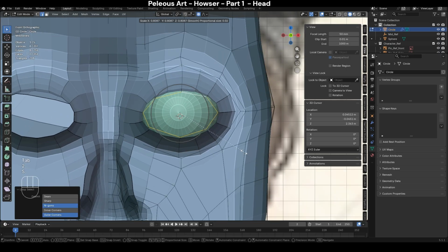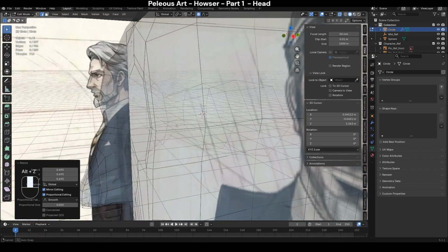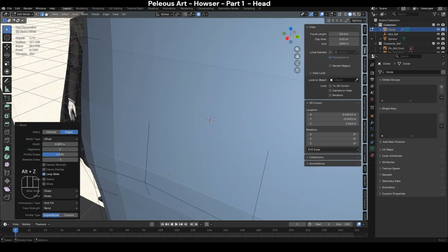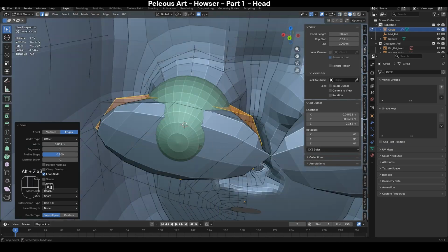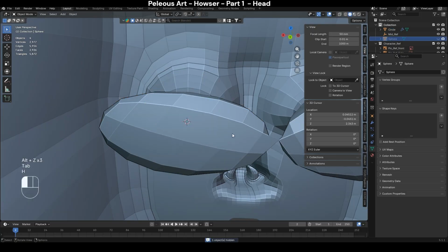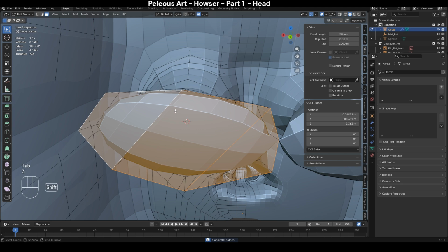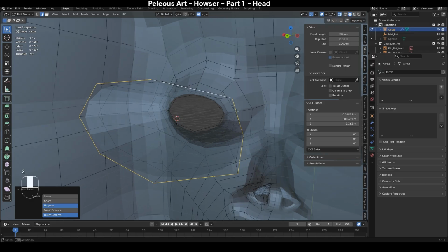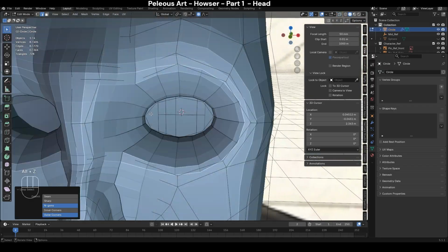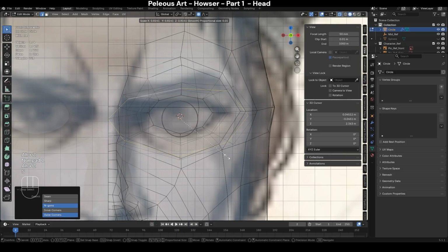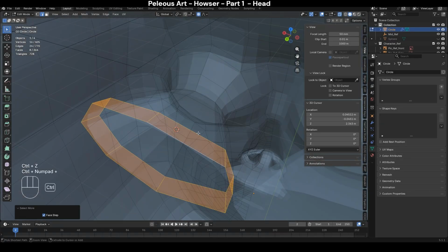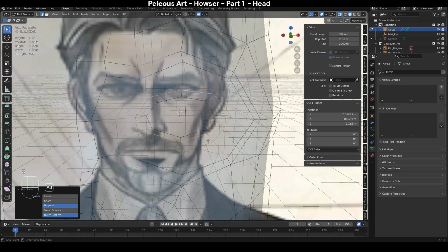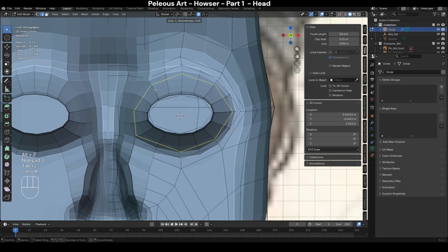Grab the edge around the eye, the inner one, not the outer one. You see what I did there? And then this one we're gonna bevel. So this one is the middle one inside the eye socket. You see the one that is marked. This one we're gonna delete because the grid fill is not what we've been looking for. So we'll select the whole edge, and we'll deselect. We'll scale it down just a bit. Let's Control plus to select, and then we're going to delete it. Then we'll do it much better later on.